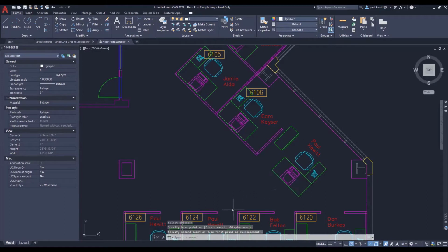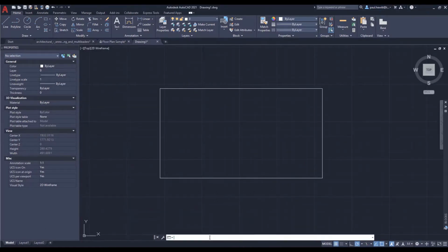The fillet and chamfer each have a polyline option, so you can edit all vertices of your polyline with just one click. Even the zoom command has options such as all and extents. Accessing these options is as easy as entering the highlighted hotkey or by clicking the option word. If you have dynamic input turned on, all of the same options are available from within its pull-down menu.